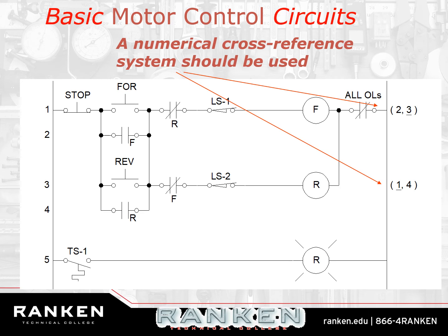Most of the time when you're troubleshooting this, you won't be able to hear the motor turn on, or you won't even be able to tell that the motor turned on. You'll have to take it for granted that the motor turned on. Why? Because that coil pulled in. Well, how do I know that coil pulled in? Well, because that closed and that opened. Right? And I can troubleshoot that electrically.